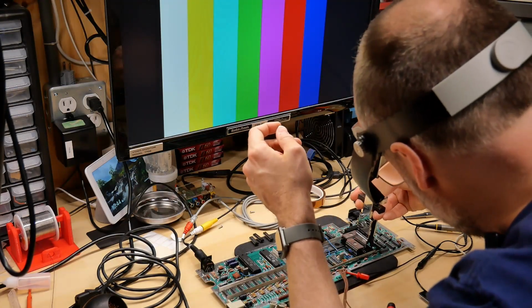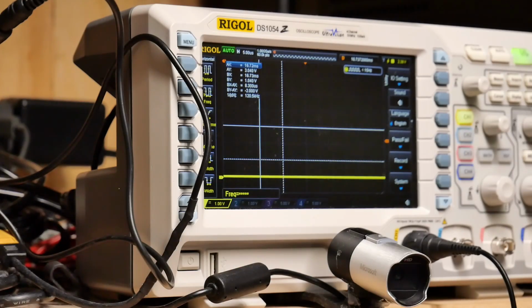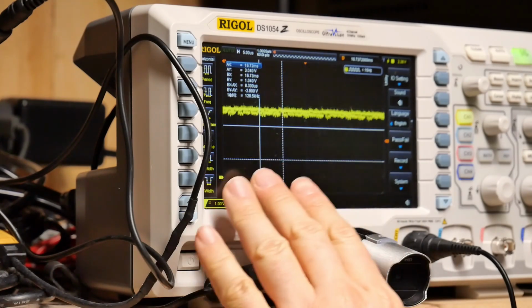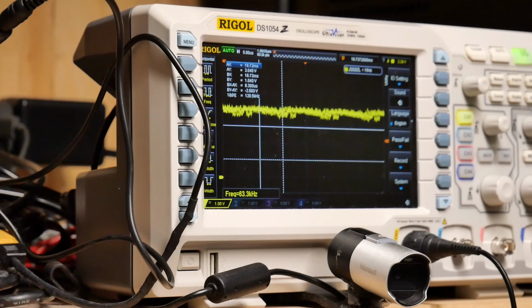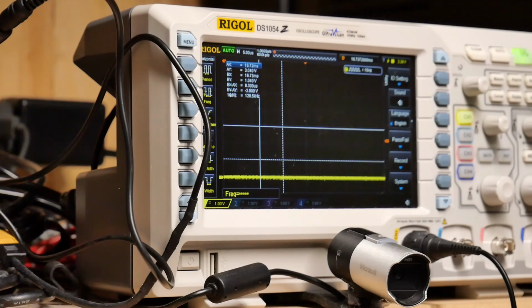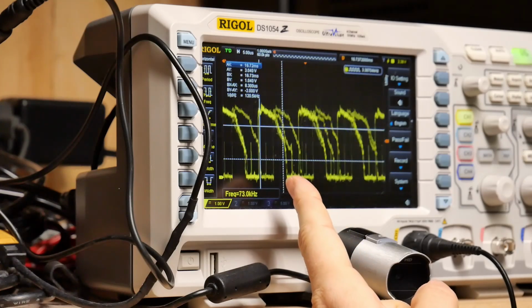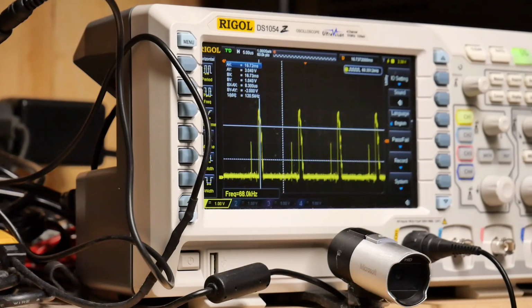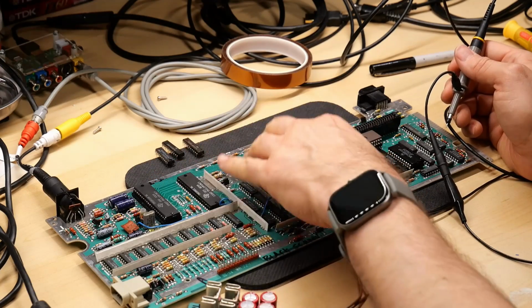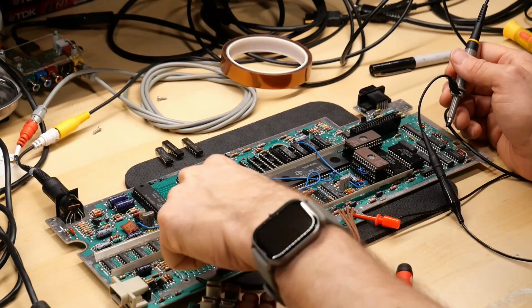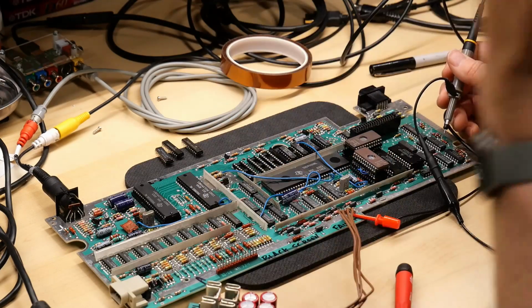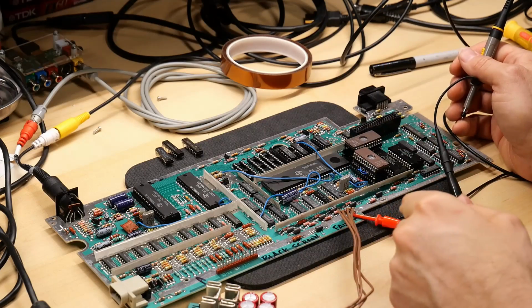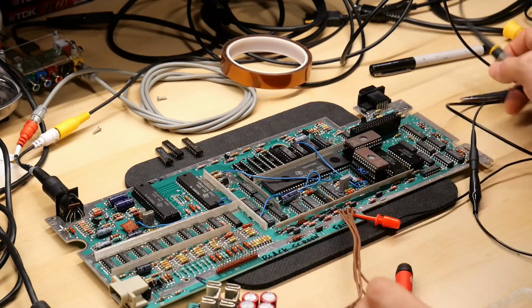All that work. I think that's the end of my troubleshooting because I've moved a bunch of chips around. I've swapped the 2 RAM chips. And yet, when I turn it on, I still see the same kind of screwy signals on here. Like on this pin here, and when I turn the computer off and then back on, you get this kind of thing going on. So that's not the RAM chip because I've switched the 2 around and that same exact pin is doing it. And I know it's not the ROM chips because of course those are new, and I've taken out these 3 bus transceivers. That is isolated. I've swapped the video chip between the 2 that I have, and literally the only thing that's left that could be causing an issue that I'm aware of is the CPU.